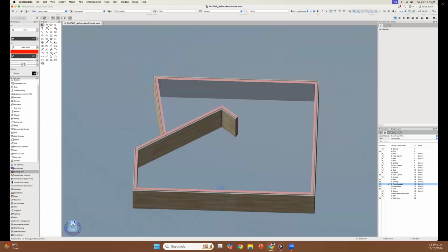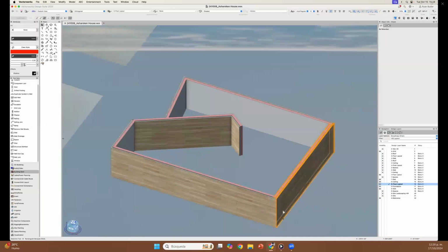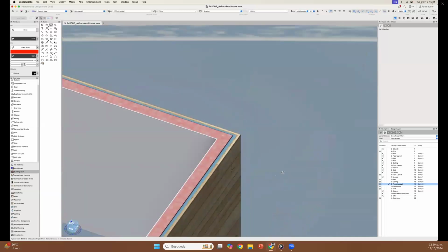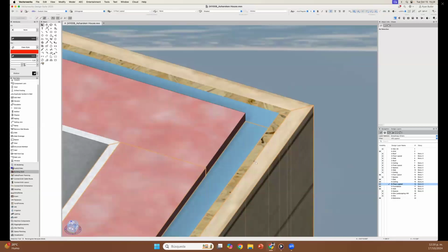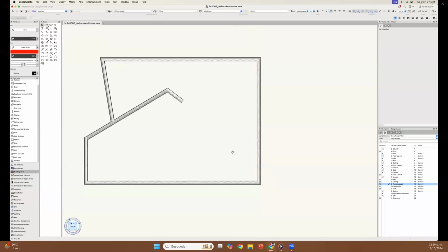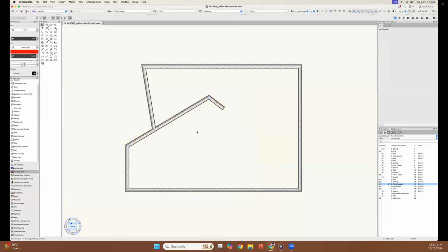Now let's take a look at what it looks like in 3D. Cool. So now you could see that the wall has components and textures and other objects within the wall. It looks like a real wall, like insulation. It has rigid insulation. It has OSB sheathing, and then wood siding as well, and also gypsum wallboard. Okay, now from here you can reverse the wall to a different side. Let's reverse this one, and so on. So you have some sort of manipulation that you can do if you want.